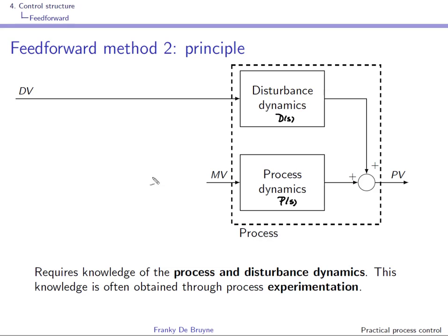And you have to collect a data set with DV and PV. Then you have to use some kind of data driven modeling package to obtain this model of the disturbance dynamics D of S.